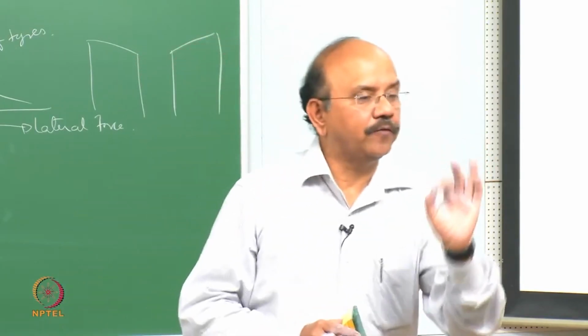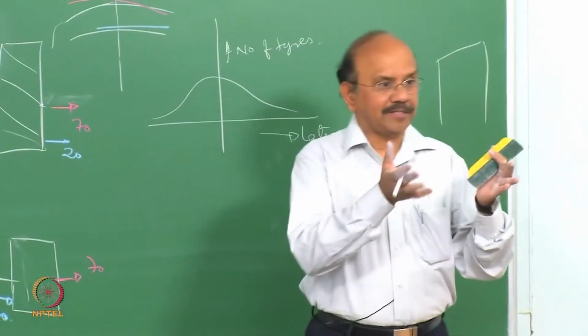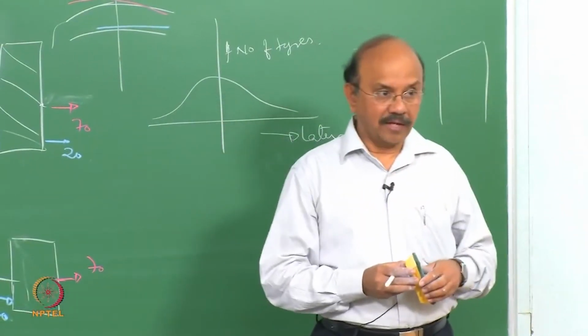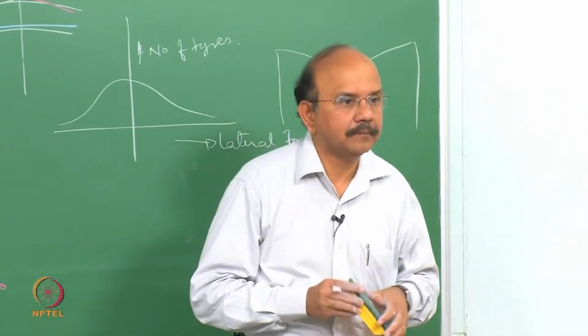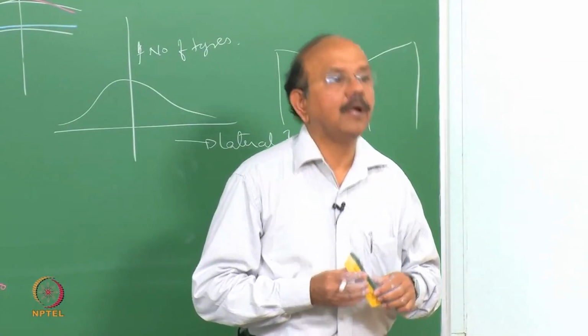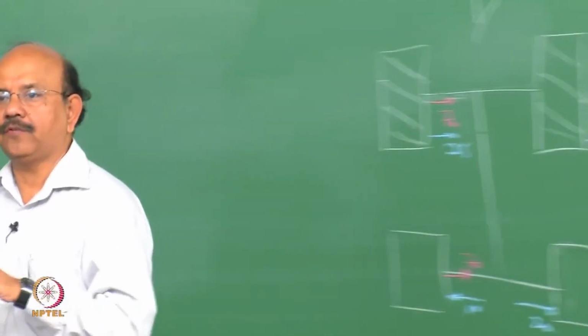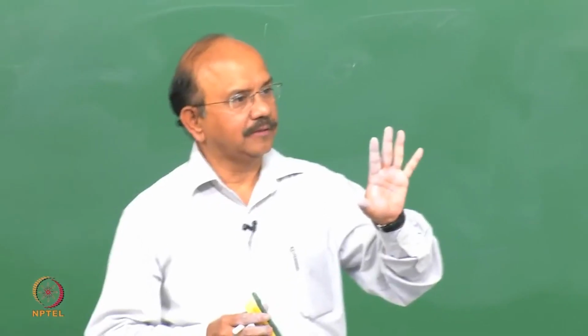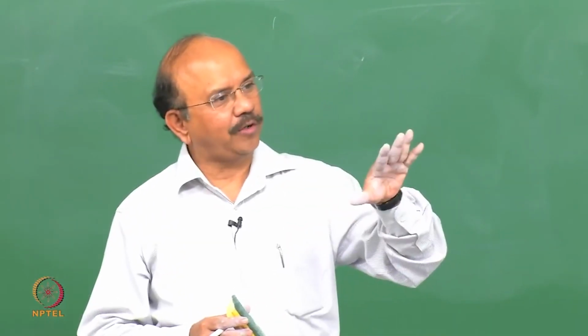Right? So hereafter, when you look at a tire, go and see what the camber is, how the wear of the tire is. Okay. Camber, we are referring camber force to be the deformation in the tire, in the rubber. Absolutely, I agree with you. So this is due to deformation of the tire, and so the origin is the tire. Ultimately, the force origin is due to an interaction between the road and the tire.